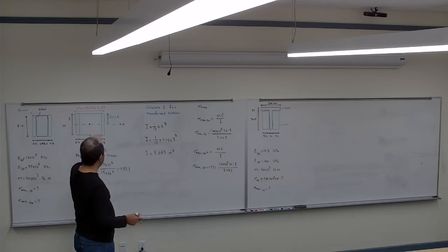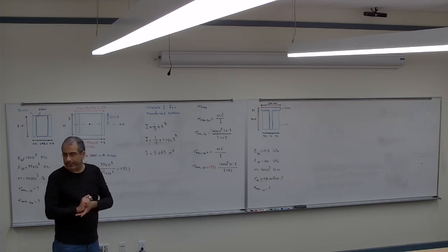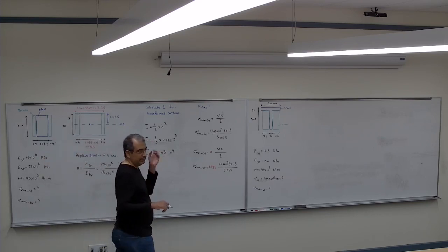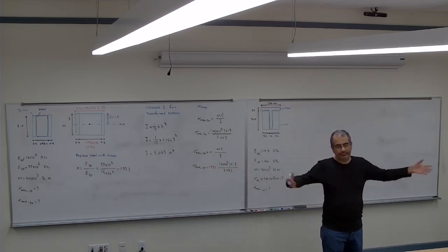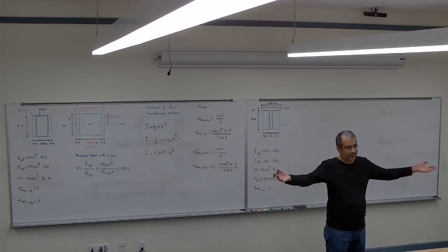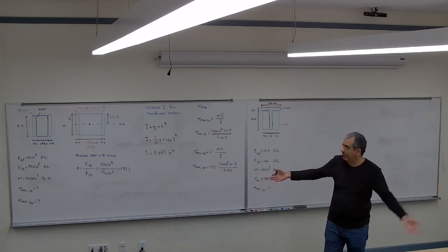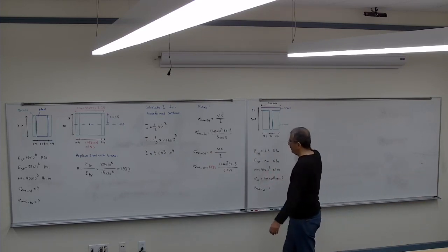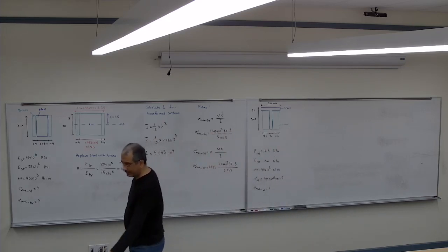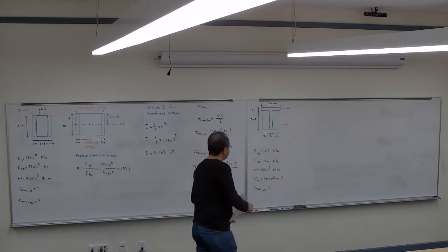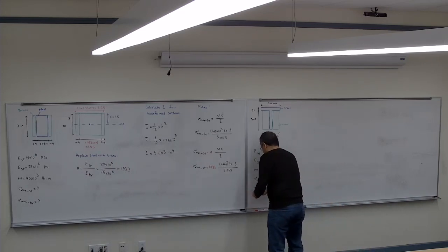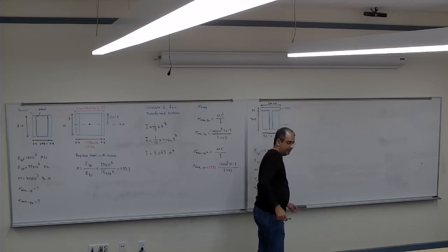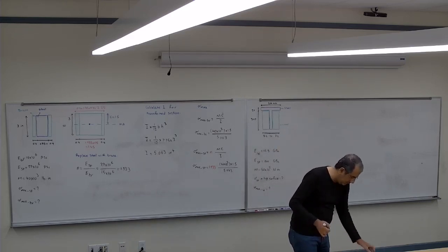So we have to convert them one to another. So I have a steel, I have wood. Again, we can either convert the wood to a steel or a steel to wood. Usually I said that it's easier to make the entire thing from the weaker material, so it's going to be wood. So it's easier to convert a steel to wood. So if I want to convert the steel to wood, what I'm going to get is a very big shape.